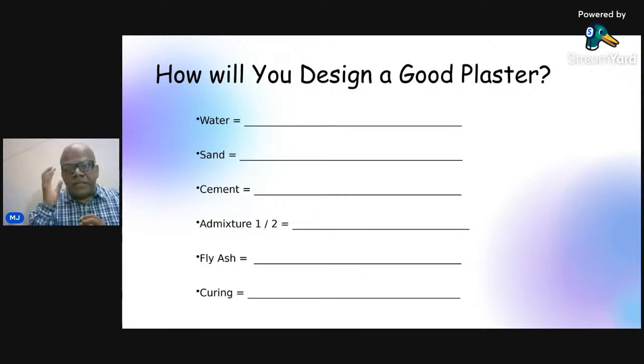And this heat which comes onto the wall creates a lot of shrinkage, a lot of evaporation, loss of water inside, and leads to fantastic cracking. So you go to any building in India, you go on the southern face, and if there is some issue in the plastering, you will definitely find cracks on the south side of your wall.